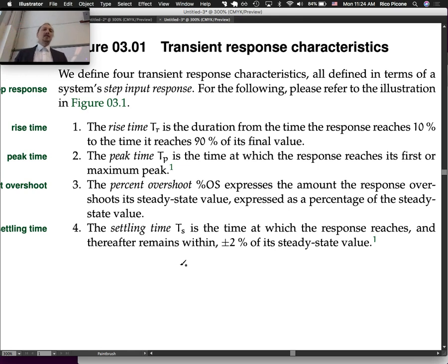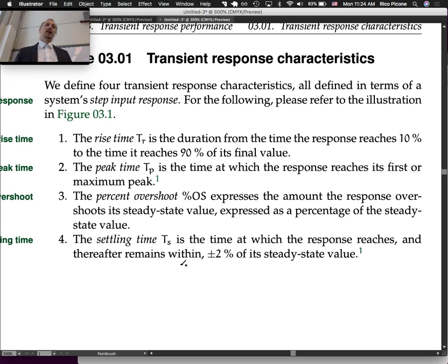And that's important. So even when we have a fourth-order system in our control system, we can test for these even when we don't have an analytic description of it. We'll test for them via simulation. That's how we'll do it. But we'll start out with first and second order systems and do it analytically. That's what the next lecture is about. So let's switch over to that.